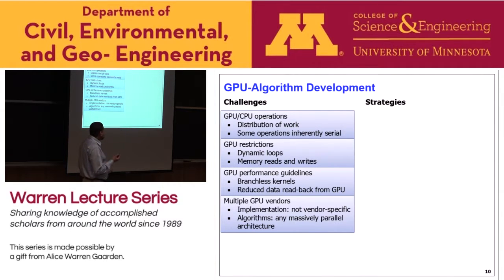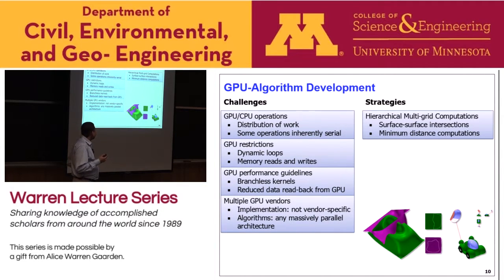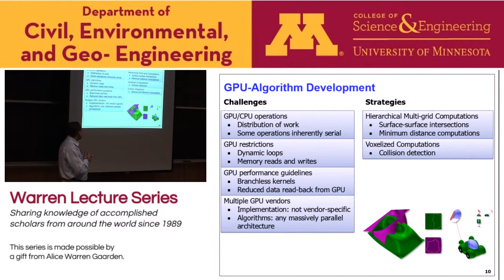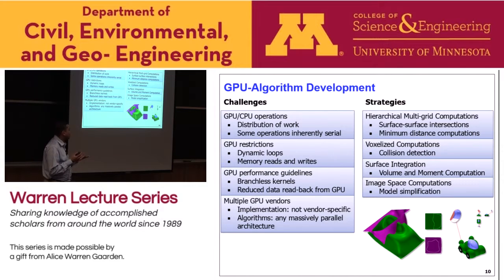So based on that, we used several strategies to do different CAD algorithms. So we looked at doing hierarchical multi-grid computations, which included surface-surface intersections and minimum distance computations. We looked at voxelized computations for collision detection. We also looked at surface integration in parallel for doing volume and moment computations. And then finally, doing some image-based computations for model simplification.